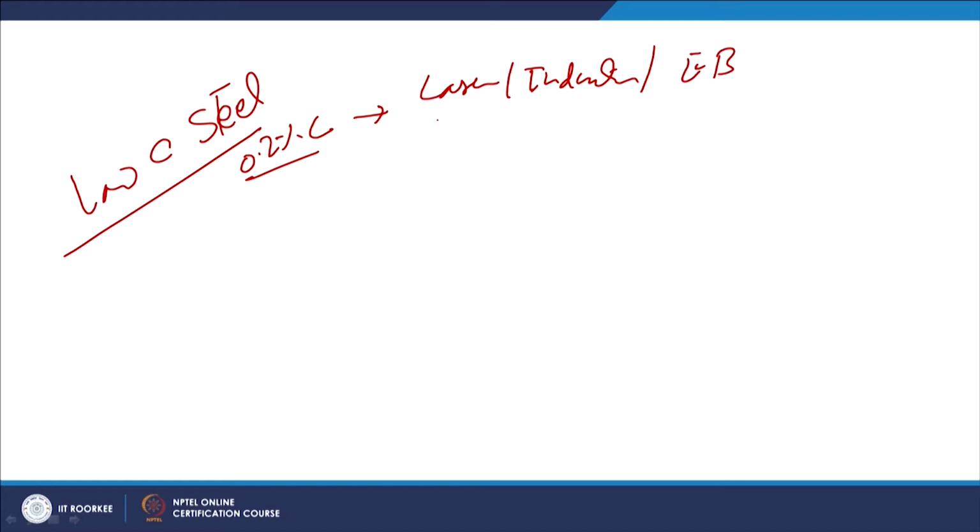So, for low carbon steels having, say, 0.2% carbon, if shallow hardening methods for case hardening are applied using laser, induction or electron beam methods, then we cannot achieve much increase in hardness despite the austenite to martensitic transformation, which may be very limited.